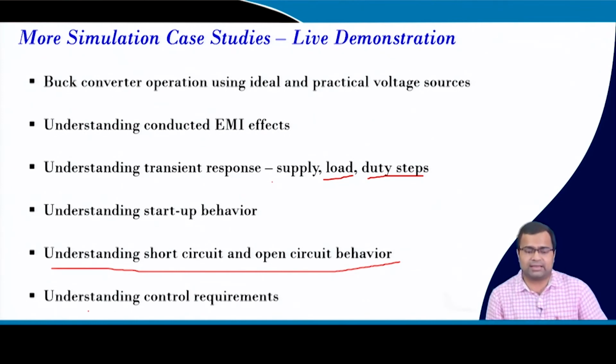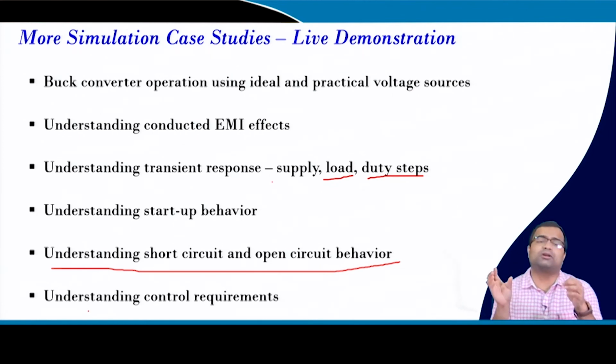So one of the requirements is to put an input filter for each converter, but putting a large input filter on each converter can affect not only the power density and size, it can also cause other problems, such as the closed loop bandwidth of the converter being affected by the input filter, and that we will also discuss in another lecture. Okay.